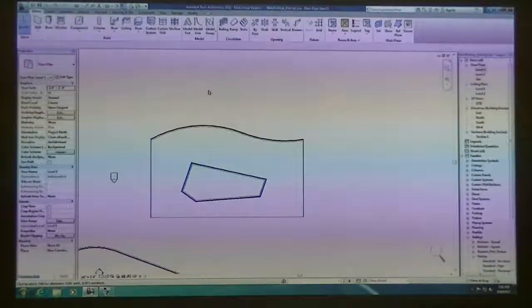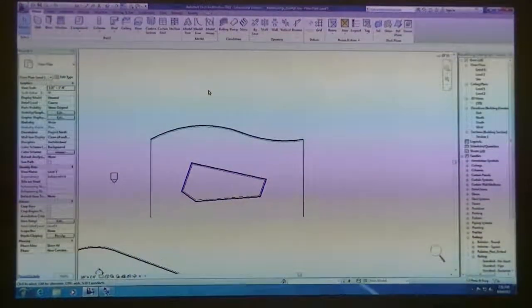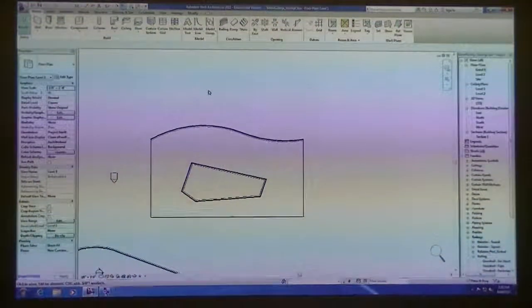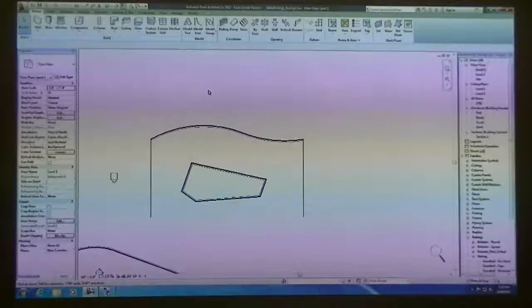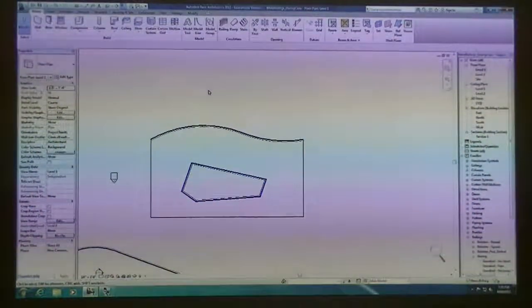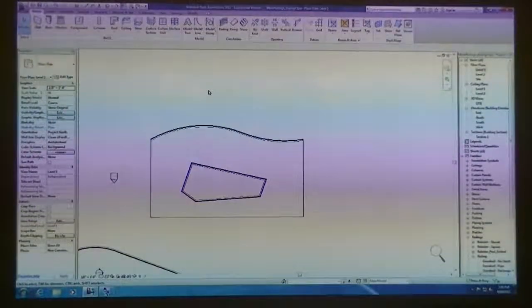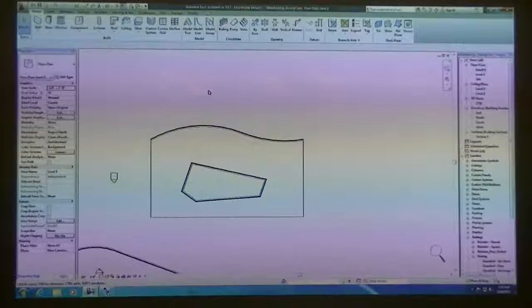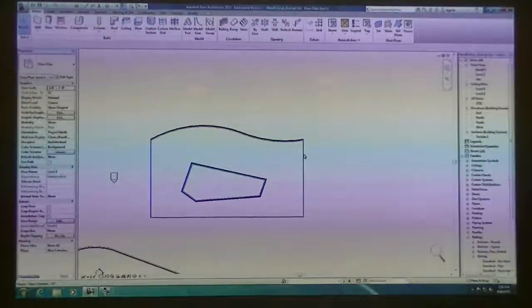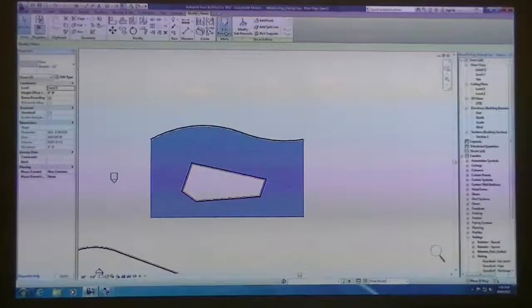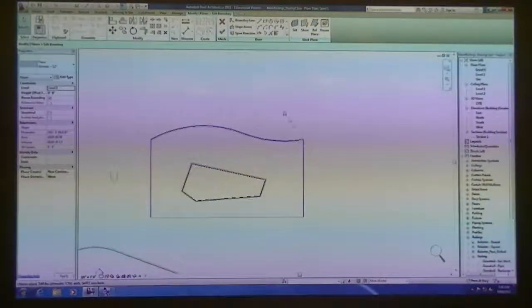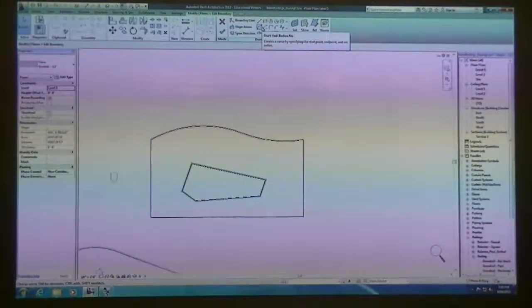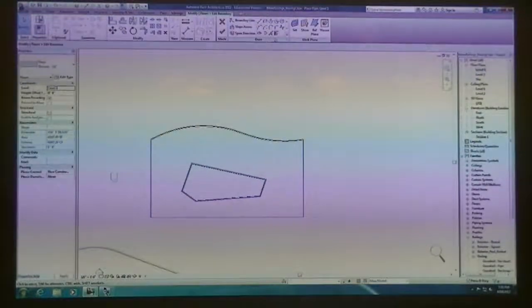Yeah, so if your floor plates are kind of complicated in that when they got cut through the mass, maybe they're curved in a sort of compound way when you look at it in plan, you can always edit. You can click on your floor plate at any time and click on edit boundary, and you may have to redraw that boundary using these tools.